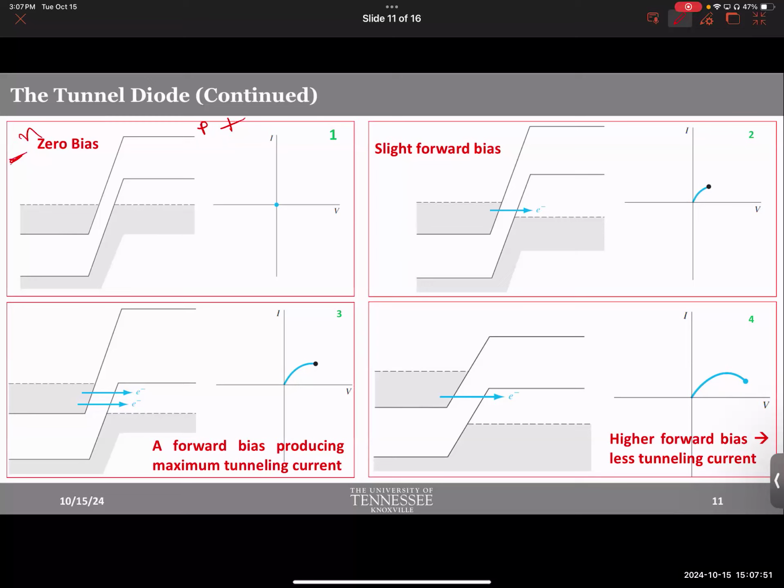So if I apply a negative bias to this, using our simple analogy that we talked about in one of the previous classes, it's as if you have added a balloon to the Fermi level, a helium balloon. Negative bias is like adding a helium balloon, and positive voltage is like adding some weights. Didn't I talk about it? Okay, so what happens to the Fermi level to the left? Folks, it should go up.